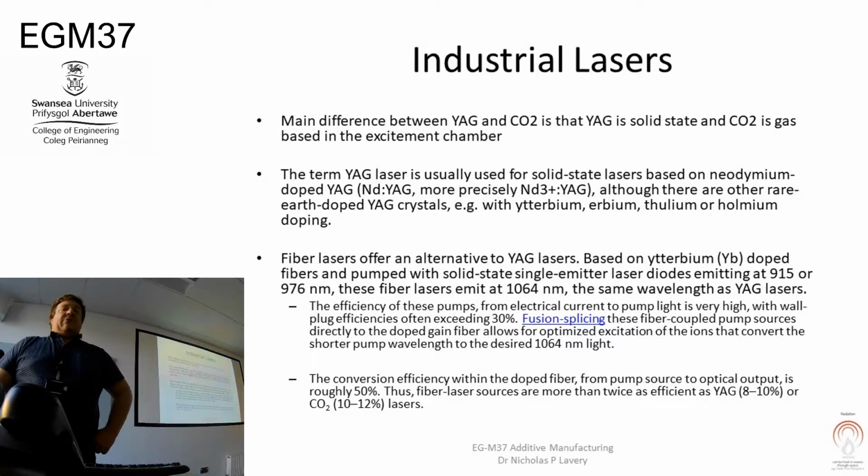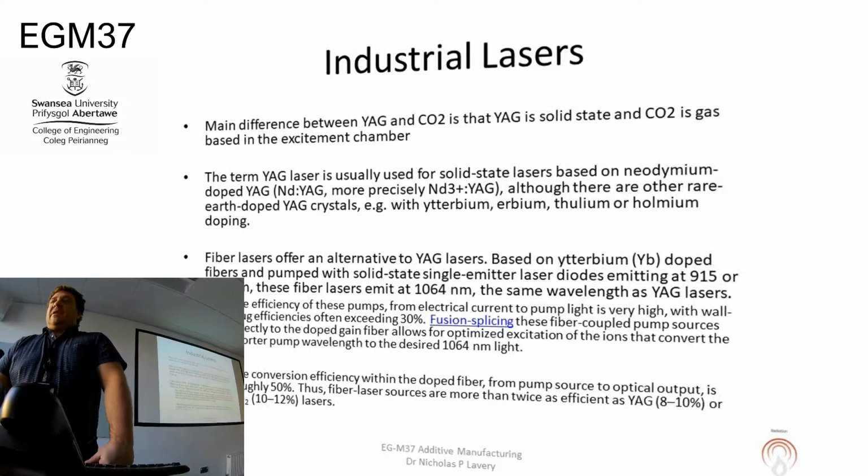They're relatively cheap and robust. They are certainly much more efficient than the YAG and the CO2 lasers. So those things count. Also, at the wavelength that they work at, they work better at melting small amounts of material within the spot size that they work with.